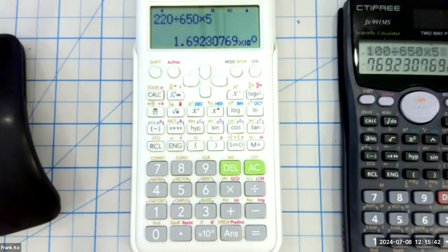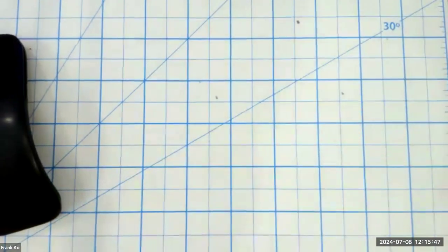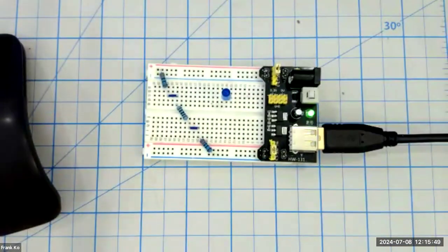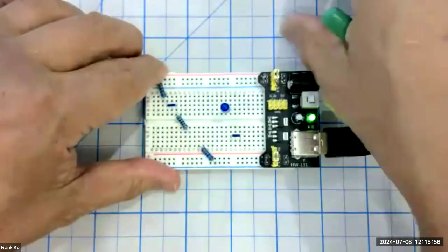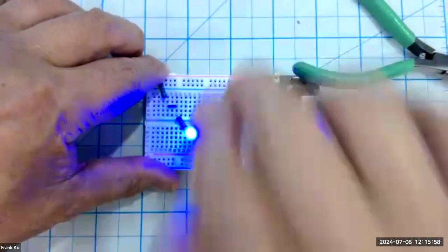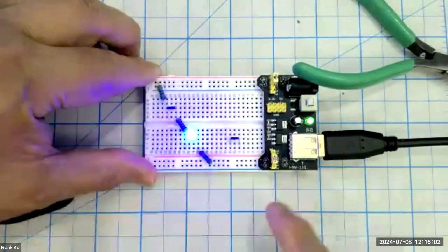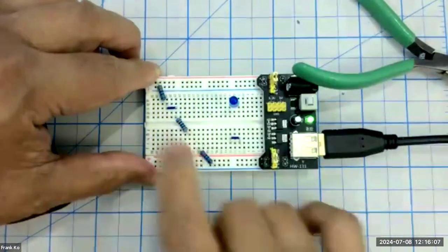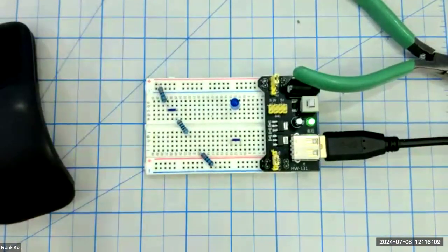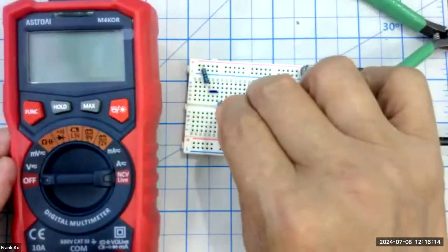And if we go to check our measurements, we could do that very easily by doing this, move this out of the way. Here's your 3 resistors. And as I've said before, in your circuit building process, I'm going to yank out this jumper just for a moment and put in the LED. The LED is nice to show us that, yes, the circuit is lit. We have current flowing through. It is built properly. We'll take the LED out. When the LED is out, you can measure the resistances individually to confirm what it is that we have.